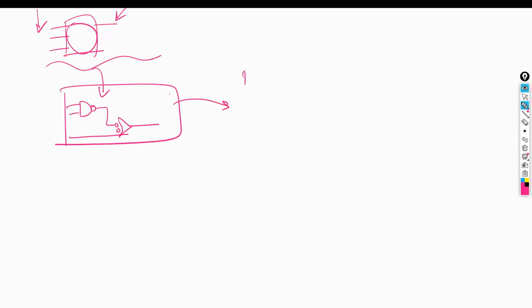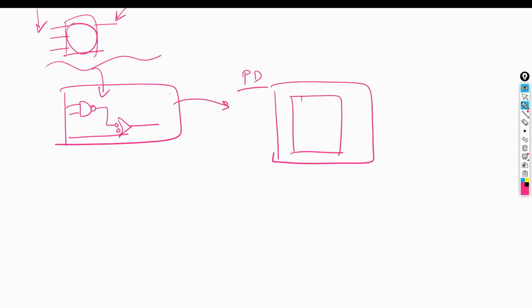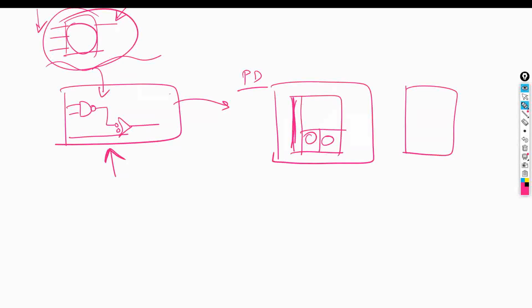Now we'll move to physical design. In physical design, you'll have the die area. In the die area, you'll do floor planning. Let's say you partition this as your CPU space, GPU space, memory, or IO space. Then you'll place all of your macros, or your logic, or whatever design you have. This is smaller, I've given you the idea. This will be placed here in the placement stage. Let's say these are all the IO pins, and then here you have your logical cells.